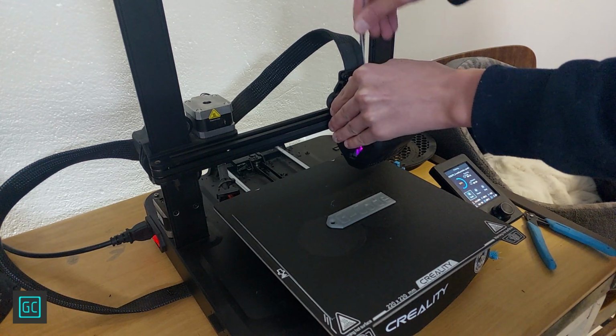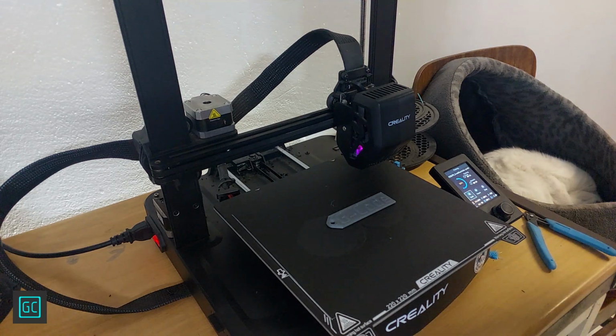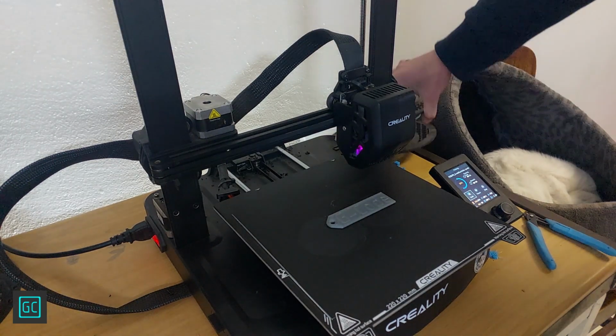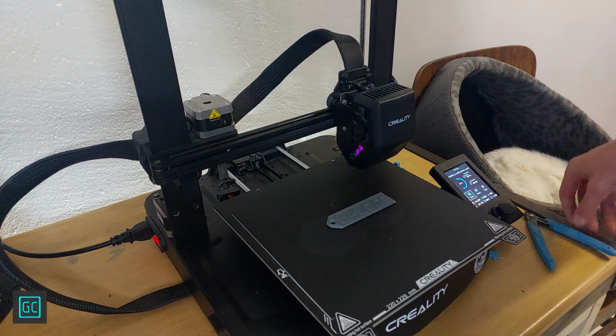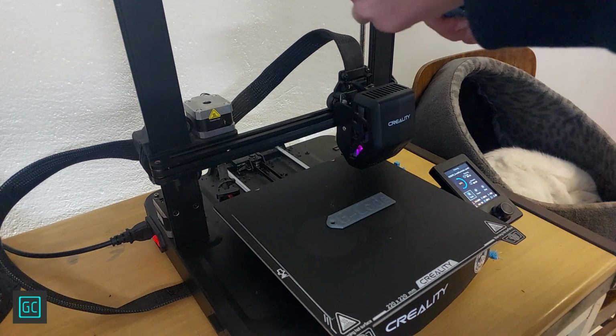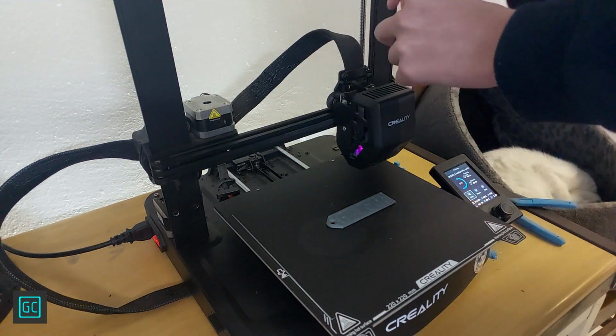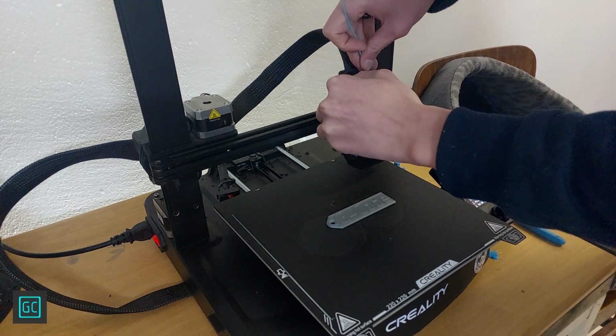There's not a lot left on the roll, but we're going to use it. So we're going to press in our plastic just a little bit and then drag it out without moving the head too much. Make sure that you don't move it. We're going to load our next roll of filament, snip off the edge just to make it easier to insert, and then we're going to insert it without moving the head too much.